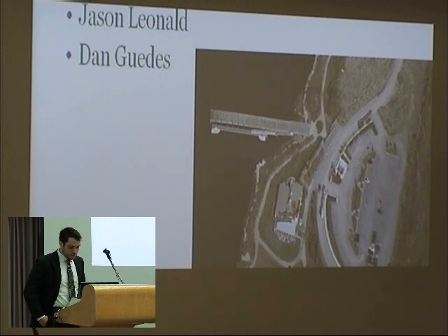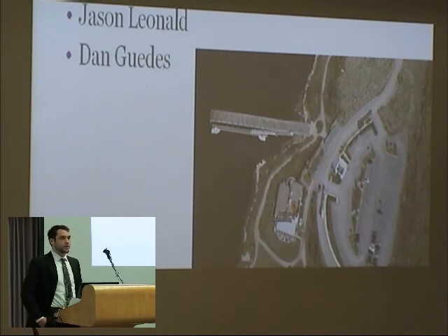One of the first things we did was consult RIDEM maps, and we found that the bedrock of the area falls under the Narragansett Bay Group. The primary rocks for this being arenite, which is a clastic sedimentary stone, and shale, which is a fine-grained sedimentary stone, both of which can be seen in the preliminary boring log investigations.